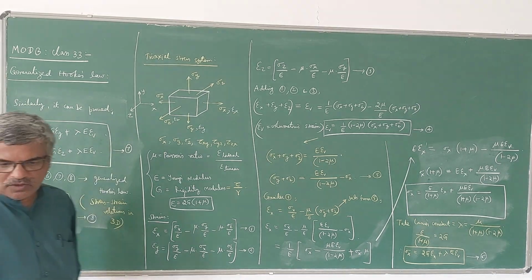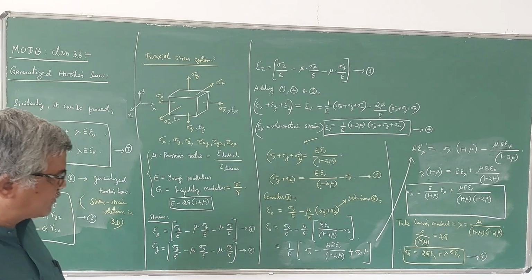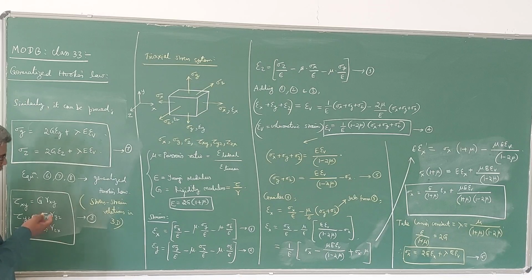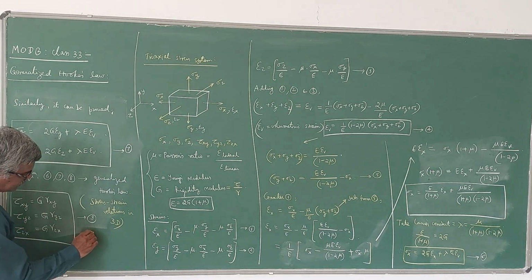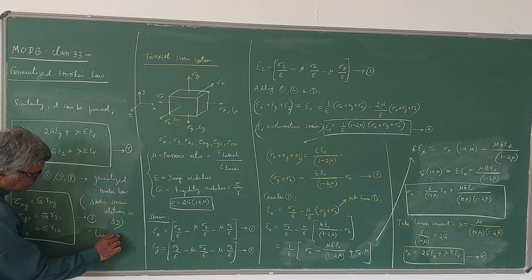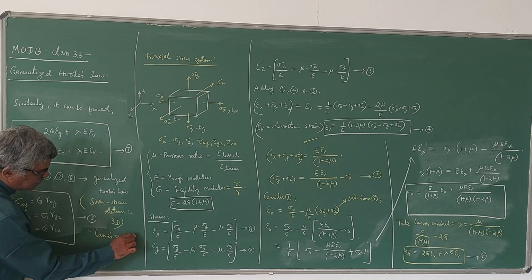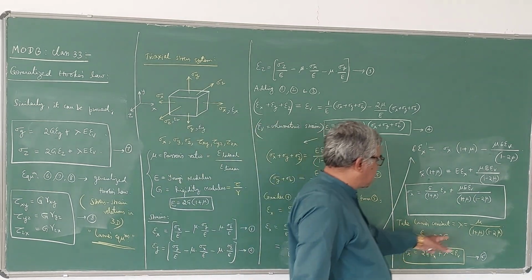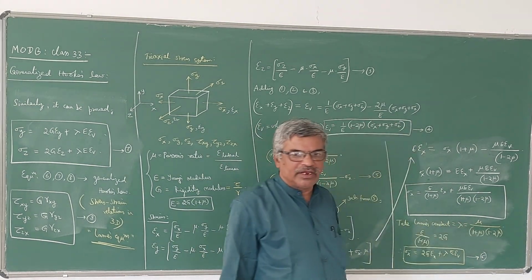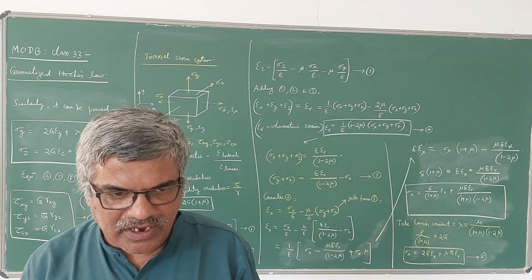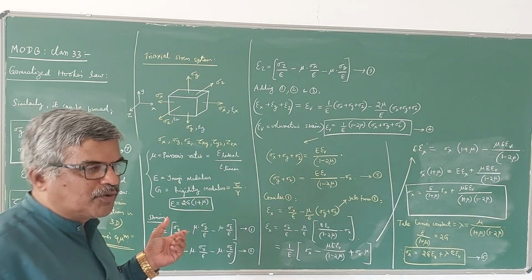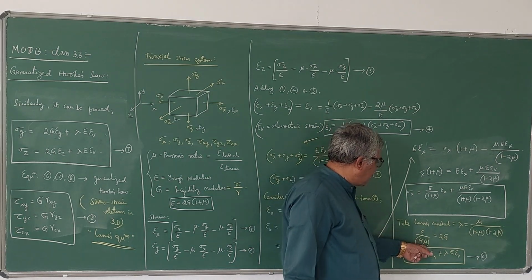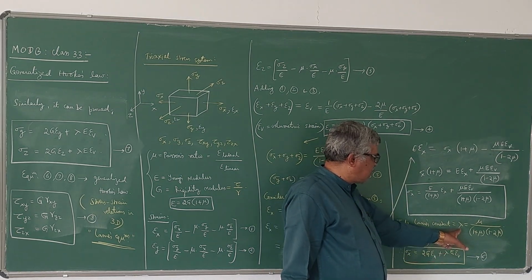Of course, in a 3D stress system. So using this, we can solve some problems. Knowing the strain, you can find out the stress and vice versa. They are also called Lame's equations, because Lame's constant lambda is involved. By knowing mu, you can find out lambda. Mu will be 0.3 or 0.25 for steel and concrete. The maximum value of mu is 0.5, which we have learned. By knowing the values of E and mu, you can find out G also and lambda also.